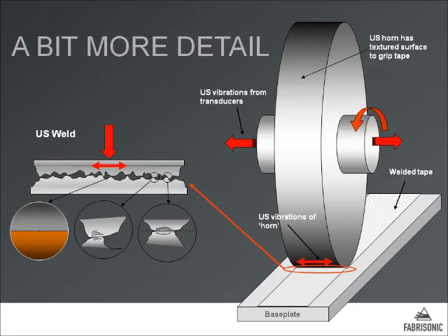Ultrasonic spot welding is a metal welding technology that's been around since the mid-60s. It's used widely in electronics and small packaging to weld spots or small areas of thin metal films together. What we've done with ultrasonic additive manufacturing is take this ultrasonic spot weld and make it a continuous process with a continuously rotating ultrasonic horn. It's a disc that rotates and rolls over the foil material as we want to bond it. The ultrasonic bond is well understood as the technology's been around since the mid-60s.